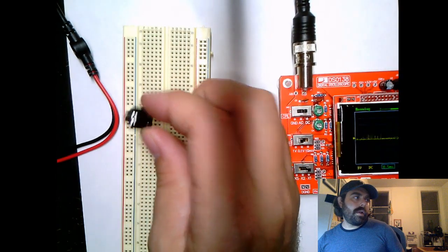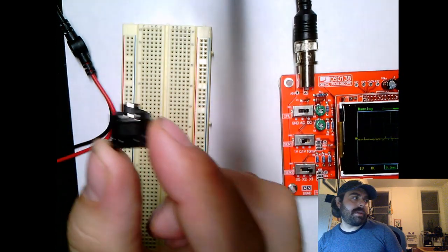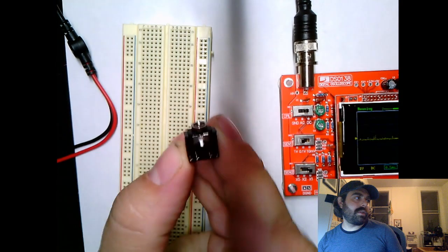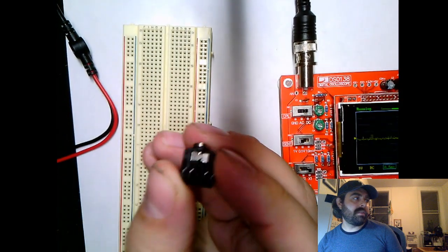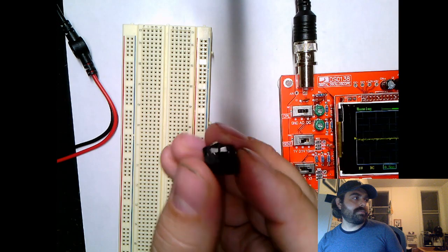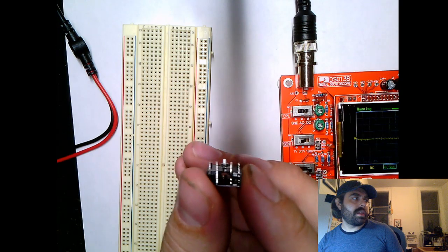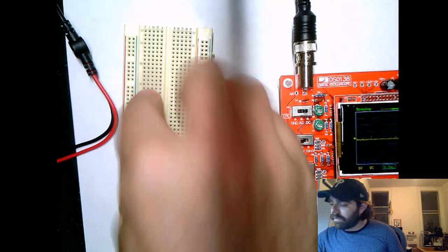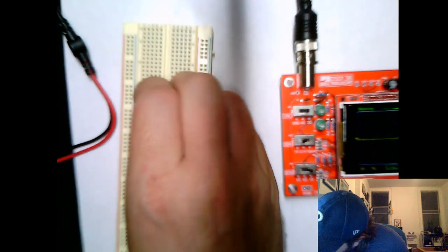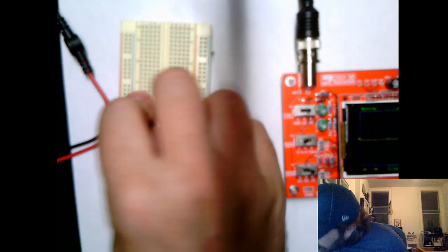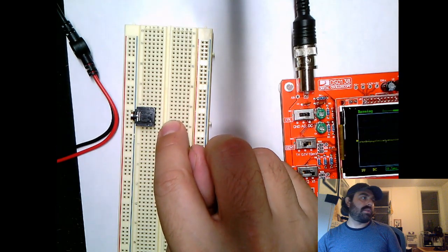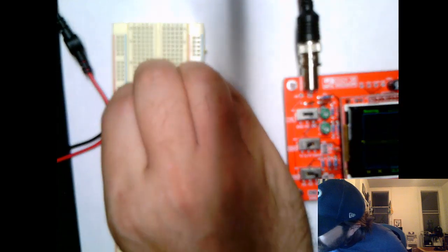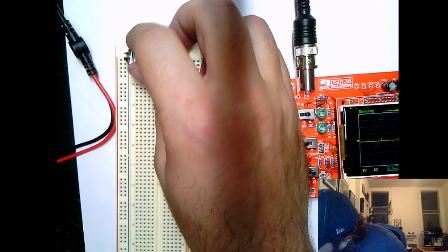Now, you should all have an audio jack. I think yours is maybe a little bit different than mine. Hopefully it's a little easier to work with. How this jack works is there are 5 pins, 2 on each of the outsides, and one in the center. When I place this in the breadboard, I want to make sure that each of those has its own row, and I'm going to position it so that I have a little bit of room behind it to plug in wires. Now, when we use these, I'm actually going to just move it to the top so that I have some space to work with here.